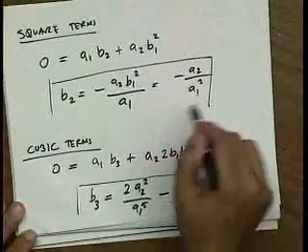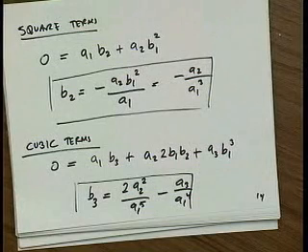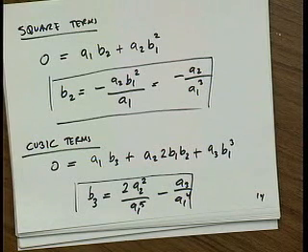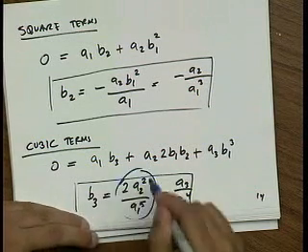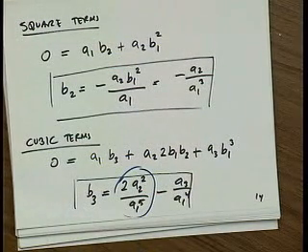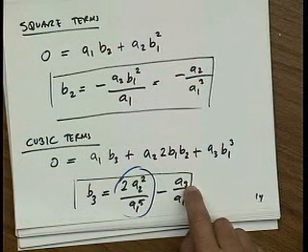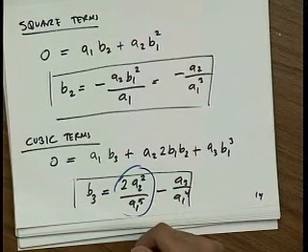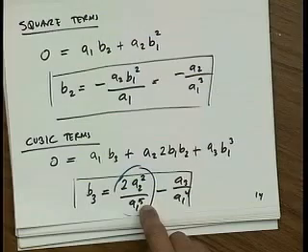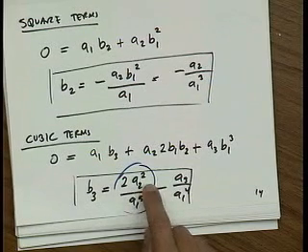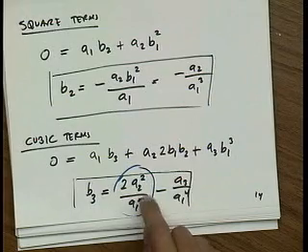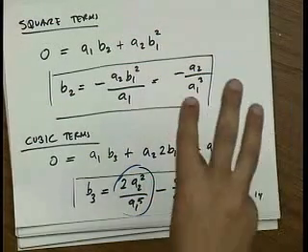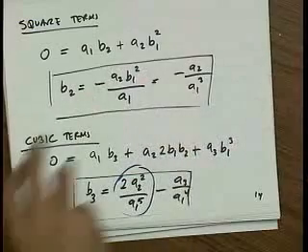So this is a nice trick to have if you find yourself in a situation where you know the reverse of what you want to know. What's also really interesting about this equation is this term. Let's say our original relationship had A3 equal to 0. That means that in the inverse relationship there is no cubic term. When I invert that equation, though, boom, I can have a cubic term. So A2 interacts with A1 and produces a cubic term in the inverse. So just because the amplifier output to input relationship doesn't have cubic, doesn't mean that the inverse does not.